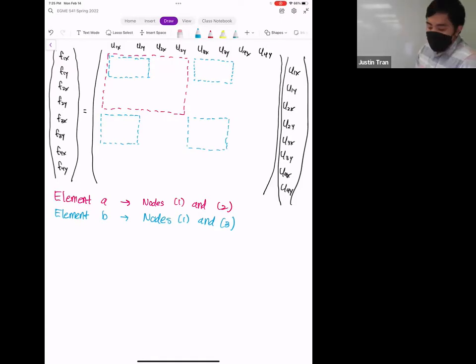So remember, be careful about these systems where you have to break it up, because a lot of times it might not be obvious. But for 2x2 systems like this, the X and Y components of each of the nodes are clustered together. And so make sure you keep those together. For 2D problems, you're going to break up your element stiffness matrices, but make sure you keep those 2x2 clusters together just like that.